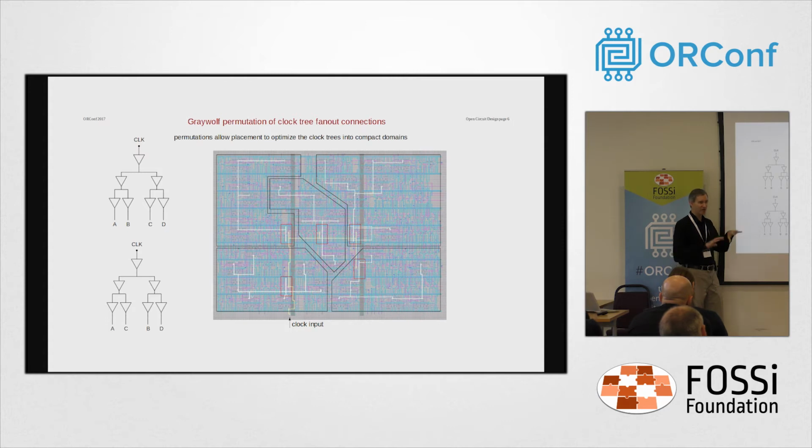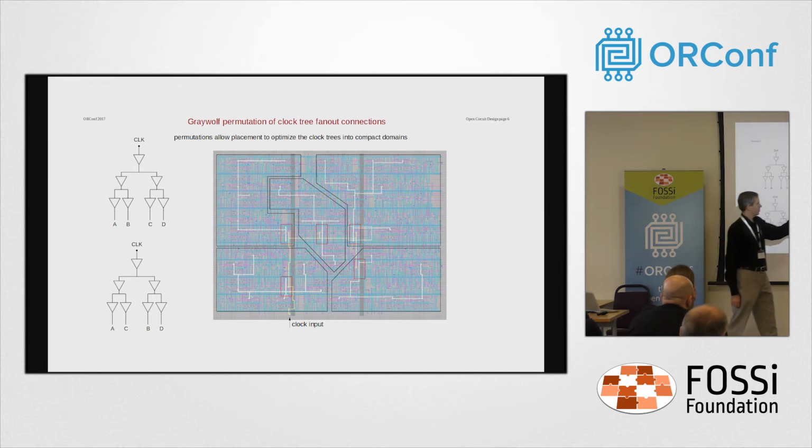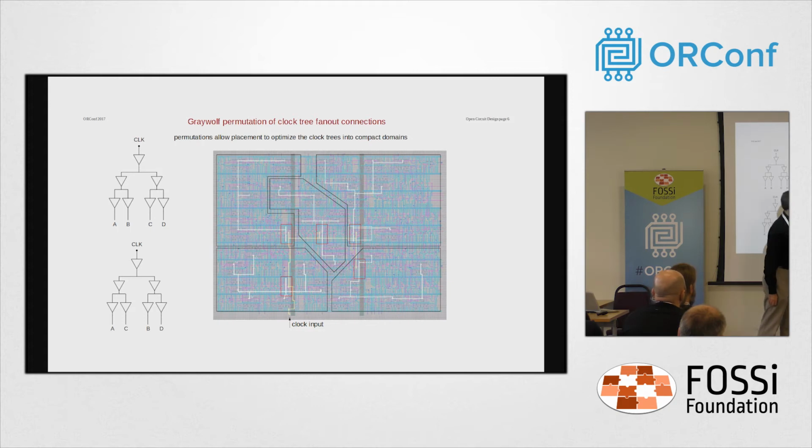And at least for a first pass, the best timing you can get is if you cluster these things so that they're balanced. So by making the placement tool treat these as permutable, it will go down and find solutions in which everything is nicely clustered. I went through one of these, a fairly small digital block, but it still shows you that once it's finished doing the placement, the clock is pretty centralized to the whole thing. The first set of buffers around the clock are clustered very nicely like this, and then that falls into 5 different clock domains in this case.